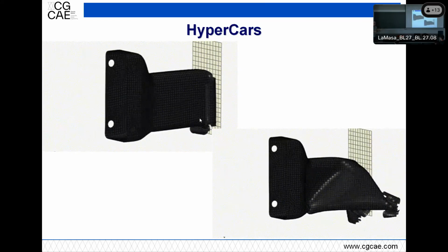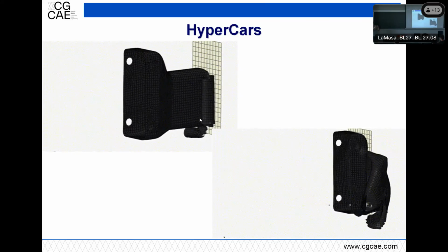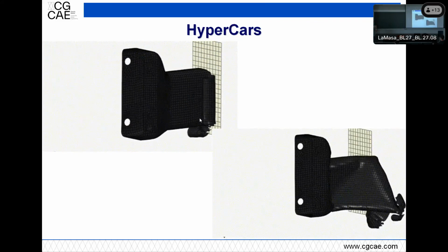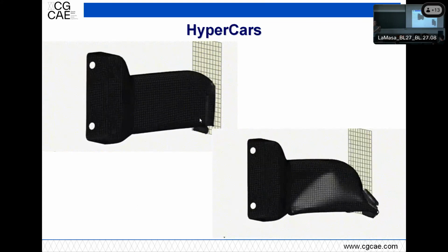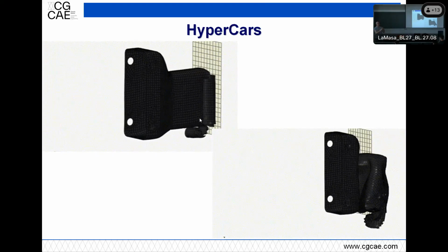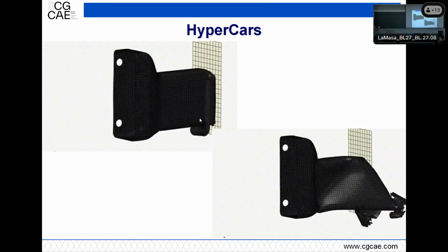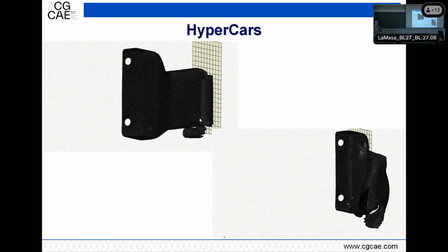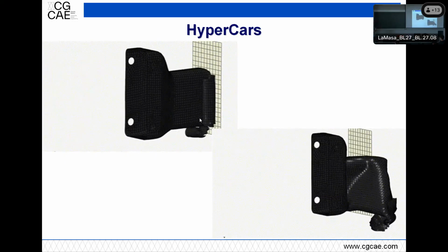And it makes the fatigue calculations more difficult, because the hollows that you have inside cannot be reached to finish treat the parts, to polish it or sand it or whatever. So you have a very rough material inside, and the fatigue limits are very low. So you might find that your part is completely okay when you look at it from the outside, which is what we are used to, because higher stresses you have in general on the outside part.